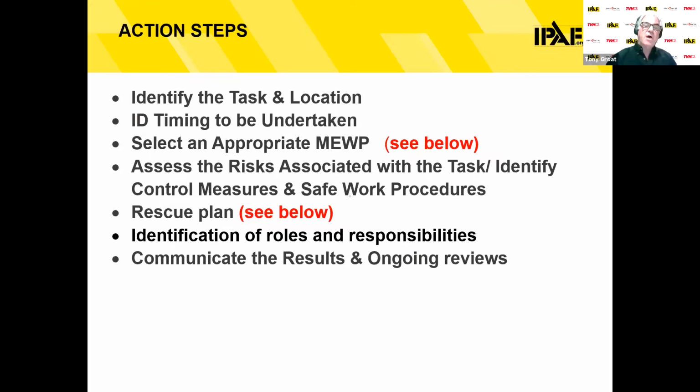And when you identify the task and when you're going to be doing this, now you have to select the appropriate MEWP. And that has enough detail that we're going to go through that as a step within our safe use program. We also need to assess the risk associated with the task to identify control measures and the safe work procedures.